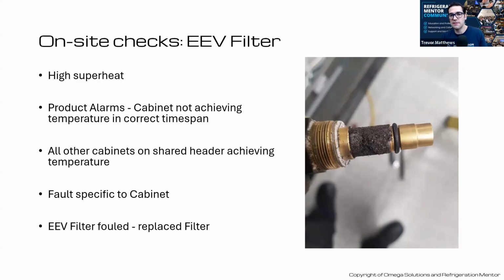It's not that the CO2 is a problem, but if you've got POE flying out with it, because we know that refrigerant going throughout the system has POE in there, all that refrigerant. So just think about that next time you're relieving CO2 out of a system. A little tangent there. What are your thoughts on that? What are your guys' thoughts on that as well?